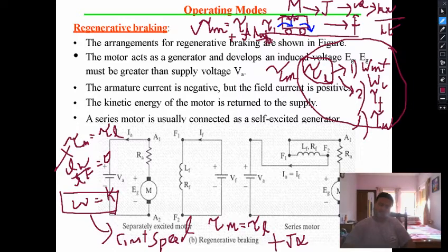So it should be plus J alpha. So it is very evident from this equation, in order to obtain this alpha, your motor torque has to be greater than the load torque. Only then your total tractive load, your entire train, will accelerate, and the angular acceleration will be alpha, the linear acceleration will be f, small f. So this is the condition, or rather it is the initial condition.